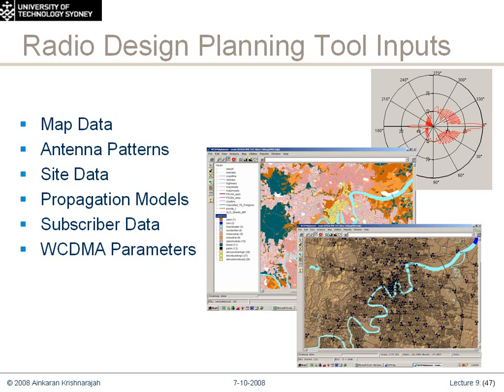The site data becomes quite important, which is the configuration of the base station, the antenna types, the antenna gain, the tilt and pan of the antenna, those sorts of things. The propagation model: how does the radio signal attenuate in this particular environment? Take a humid environment versus a dry desert environment, it actually changes the characteristics of the radio waves as well.